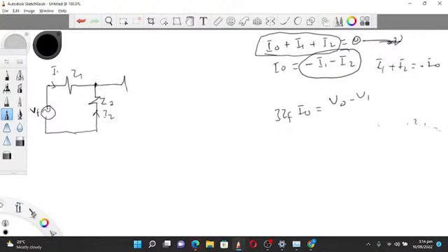And then I come and put 3ZF, and any Z0 that they gave in the question, and I give this direction. I combine the circuits, and this will be the diagram for double line to ground faults. Very, very simple. Okay, so that's what you have.